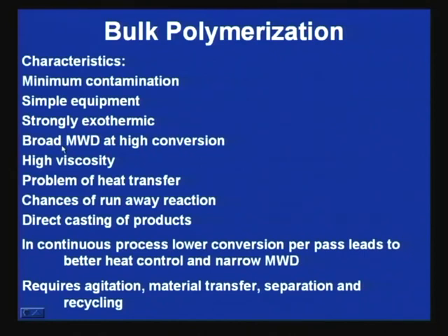Now, if one goes to higher conversion, then it may give broad molecular weight distribution. Again, here is the underlying science telling broad molecular weight distribution at high conversion. What is that science? Now, as the growth occurs, the mass becomes more and more viscous.